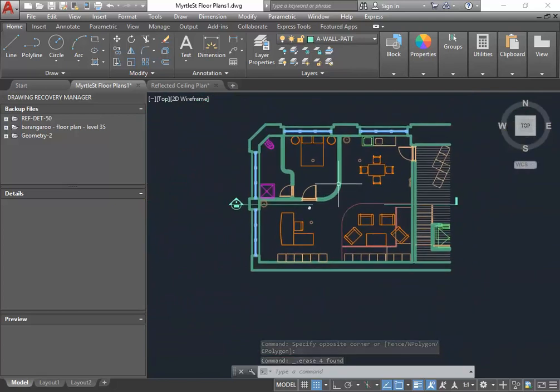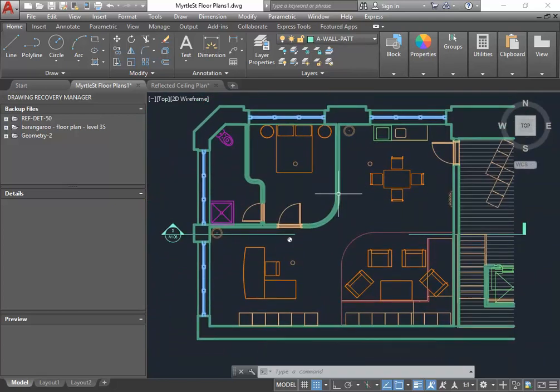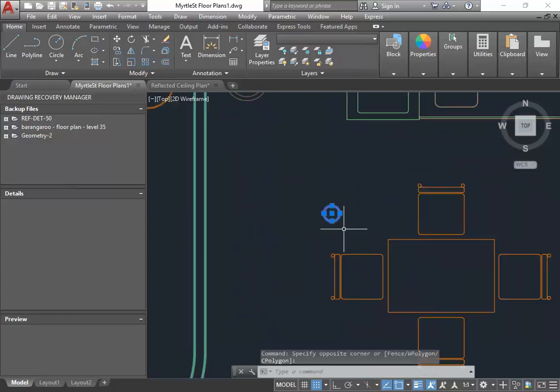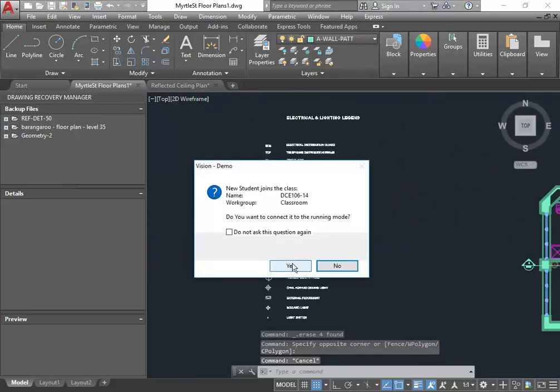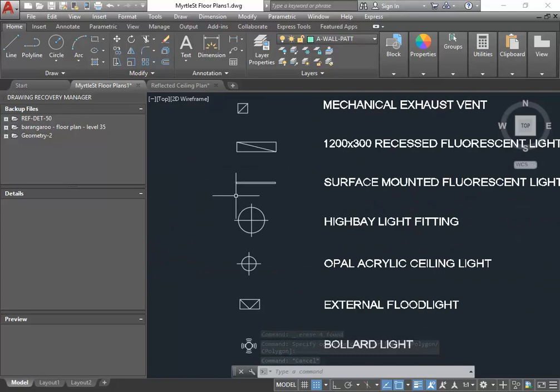And then the only other thing you probably should have on your ceiling plan, apart from maybe making stairs look a bit better than I've got them there, but we'll come back to that, is the lighting. I probably would need a few more lights than this, so it's a good chance to correct your lighting, because in Revit you'll sometimes only have generic lighting. You can always just copy light symbols if they're down lights, but in this electrical legend block, you'll see there are quite a few symbols for lights.